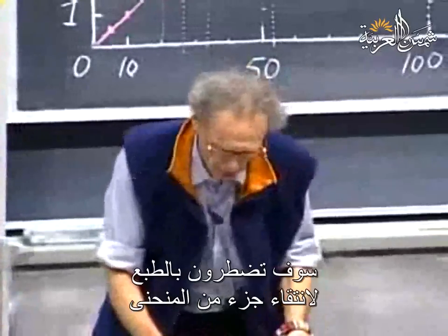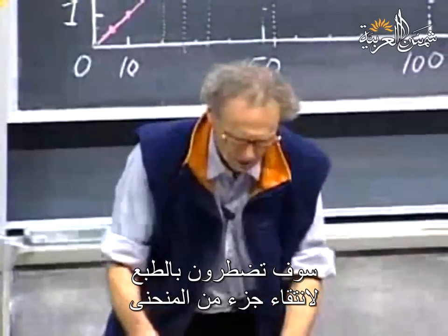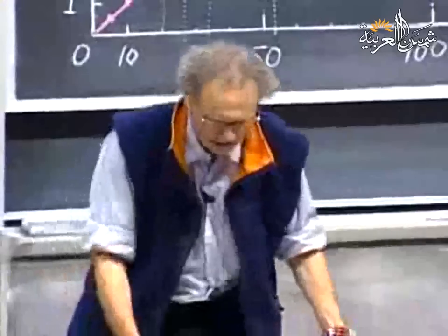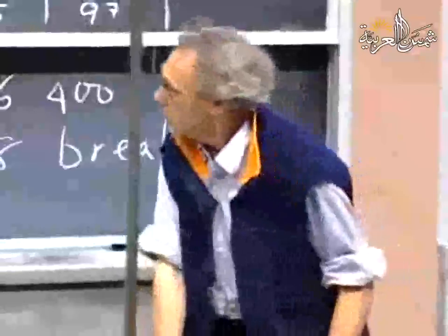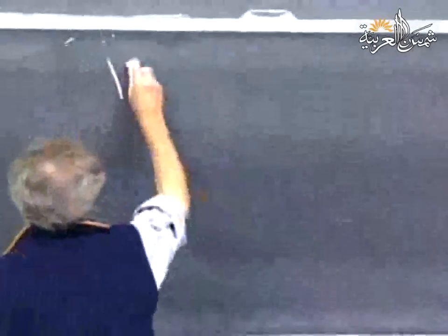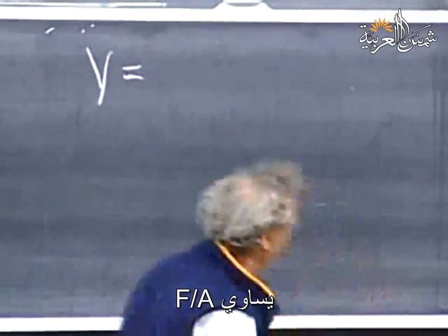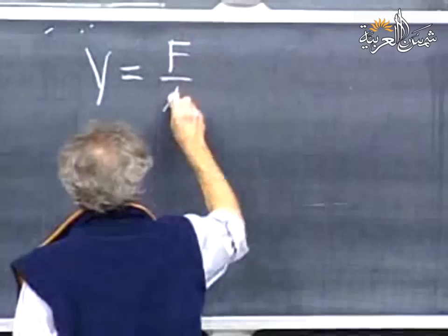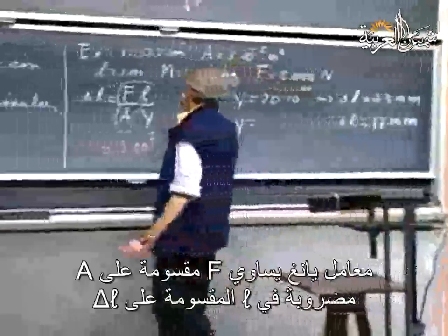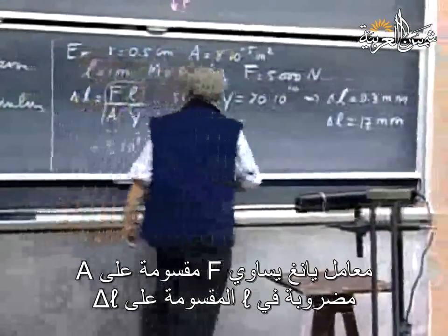Young's modulus from the data. Of course, you'll have to select a portion where you think that the data are reasonably linear. So Young's modulus itself equals F divided by A. You have here the equation, Young's modulus equals F divided by A times L divided by delta L.